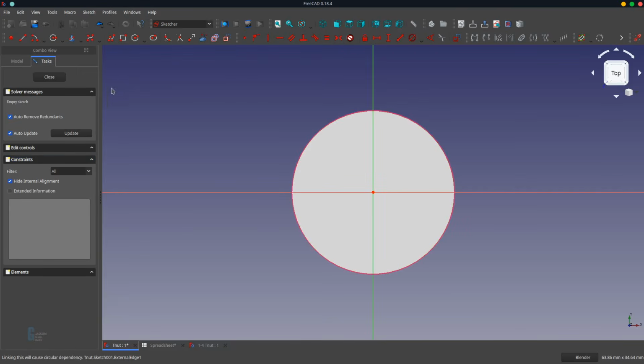So we are going to bring in the outside of the base, and then using a polyline just model the interior part of the spike pocket, and then we use an arc with a center and two endpoints to model the outer part. Now at this point we've got 1 degree of freedom, which is essentially this here, so it's either the length or the width, and I've got both of those.